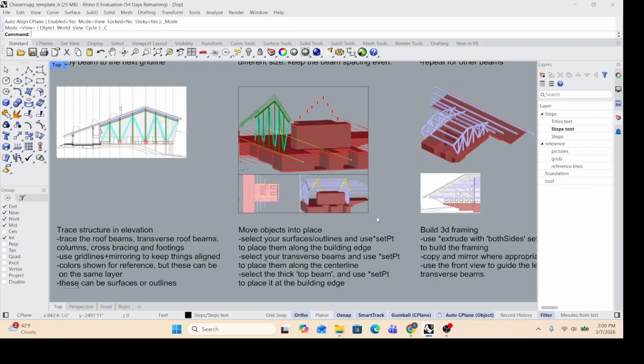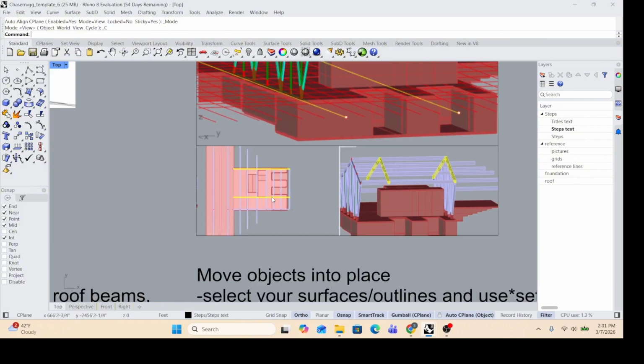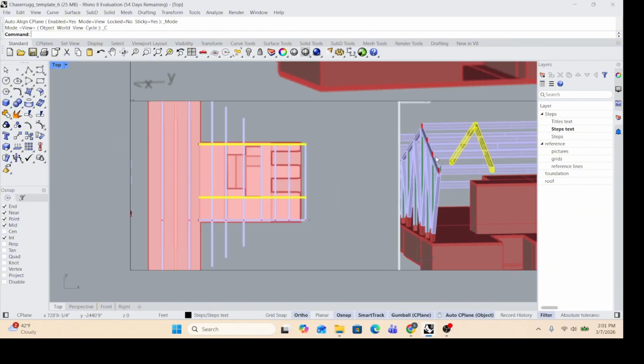So once you've made all your shapes, we're going to do this bit next where we're going to bring it out to the edge. We're going to move all the lateral beams to the midpoint because they're going to extend evenly to each side. And then just that thicker one we're going to copy as well to the edge of this wall. So you can see it pretty well in this view. So you'll have, for that 2-foot thick one, one on either side of the building. And then you'll also have one going right above this.